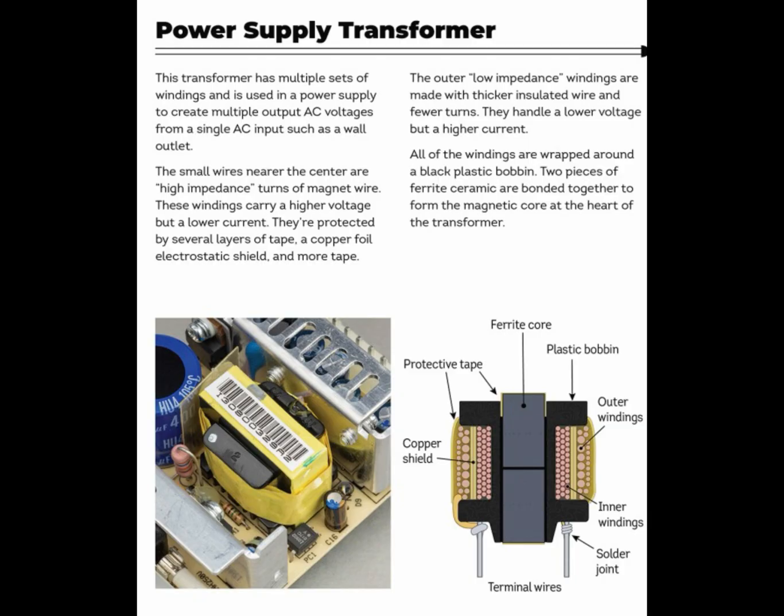It has four types. Number one is the step-down transformer, which reduces voltage from a high level to a low level. Step-up increases voltage from a lower level to a higher level. Isolation transformer is used to isolate circuits for safety, providing the same voltage level but with electrical separation. Toroidal transformer is a compact and efficient option with a circular core, reducing electromagnetic interference and physical footprint.